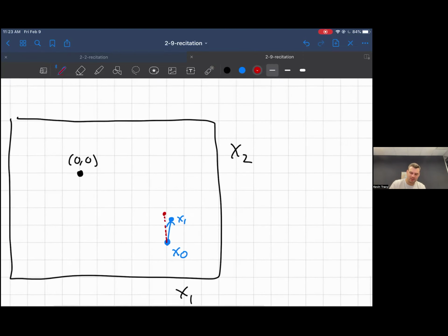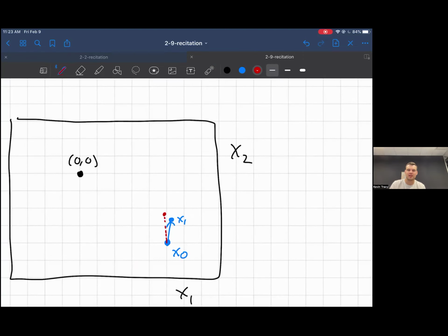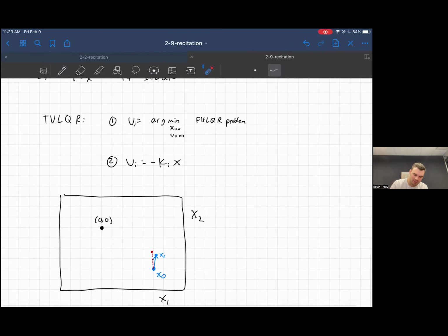And what happens there is that now that I have moved off the course of my trajectory, I can't use U2, because I'm now at a different point than the convex program thinks that I was. When I solved this problem over a discrete time trajectory, I assumed that my dynamics are going to move as my linear model says they're going to move. And when I go and practice and it turns out that there's a little bit of error after the first step, I can keep running this thing open loop, as you call it. I can just keep feeding it new controls and have it run. But the problem is I'm not taking into account this state error that I'm getting every time. And so we'll end up doing weird stuff.